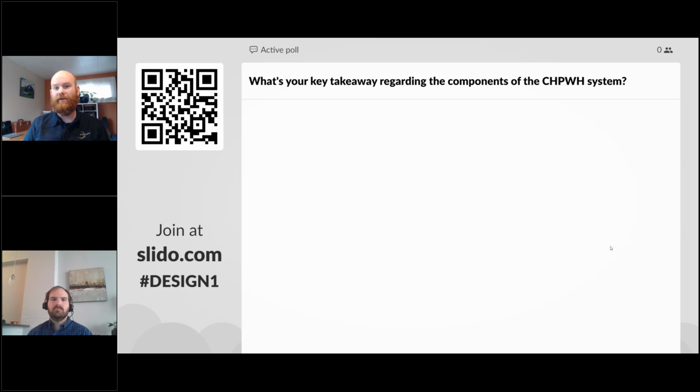That's possible. There's numerous design solutions and equipment that you can do that with. If you're looking at a VRF system, a variable refrigerant flow system that one of the big name manufacturers uses, they typically provide a hydro kit, or you can get a hydro kit, which takes that refrigerant and exchanges heat to water. And so now you can use that water heat to put in a storage tank and store it with the domestic application.